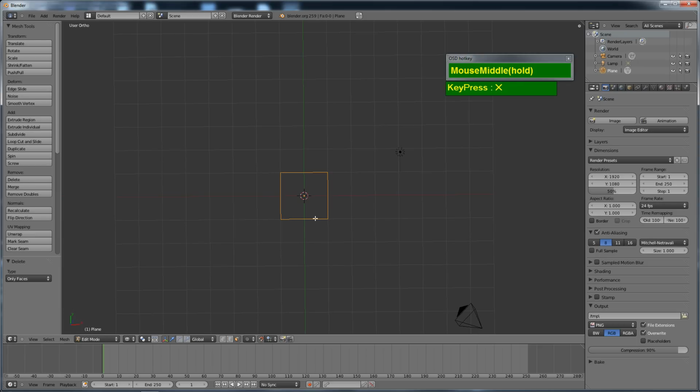Okay, so I don't need the face, and then I'm going to delete away all the 3 edges here. I notice this: when I select one of the edges, then I press Ctrl I to invert select, press X, and delete away the edges. So I only need to start off with one edge. All right, so I'm going to now turn on the vertex selection. So holding down shift, both of these are activated.